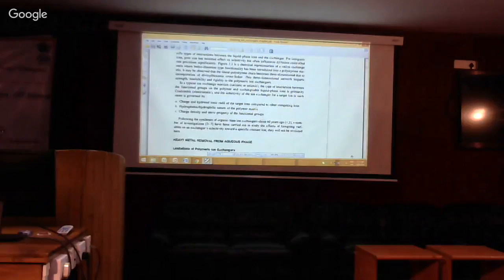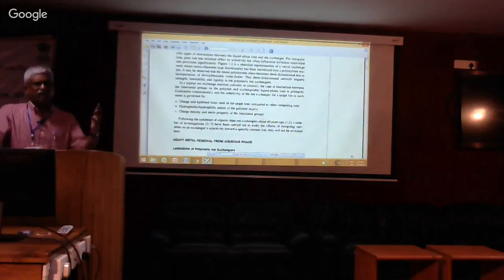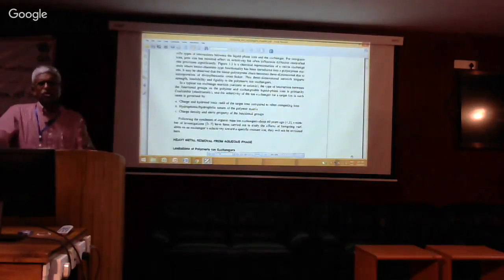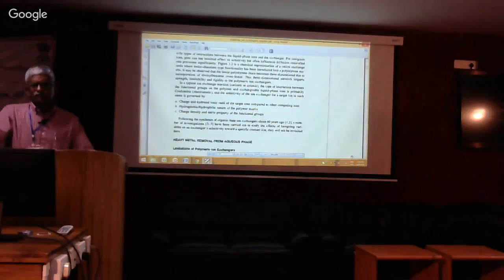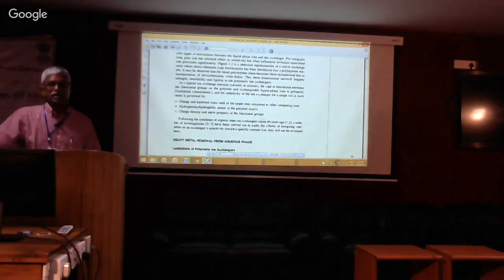So what do you do? You can't abandon the well. And removing nitrate is not very easy. If you have water which has iron, let's say, which is very common, and iron and manganese go together, removing iron and manganese is very easy. There are so many technologies. If you have hard water, removing hardness is very easy. But if you have, let's say, 10 milligrams per liter of nitrate nitrogen, and you want to remove just that nitrate, the rest of the water is fine, it's very difficult. There is no technology which can selectively do that.